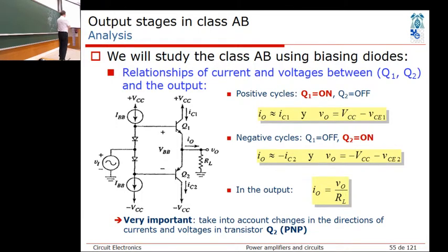Okay, that's important. When you're doing this kind of analysis, follow these Kirchhoff's laws of voltage drop, meaning the sign, and the same thing also follow the Kirchhoff's current law to make sure that you have the signs correctly.